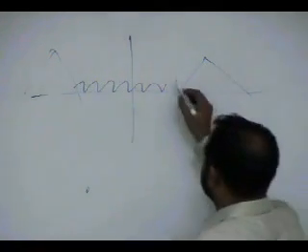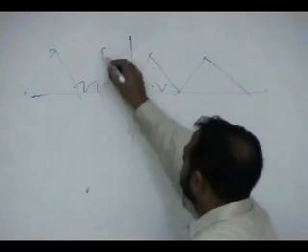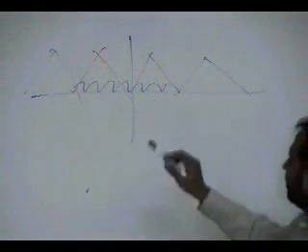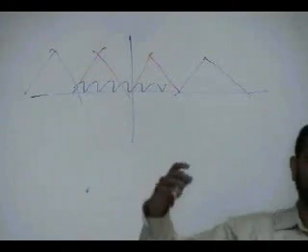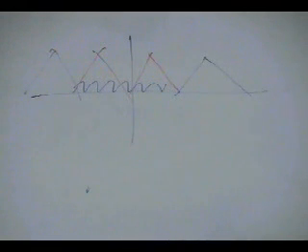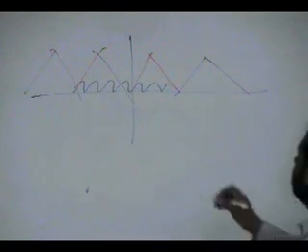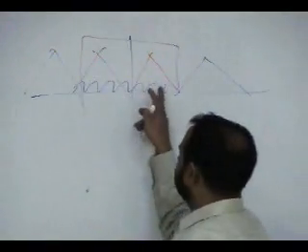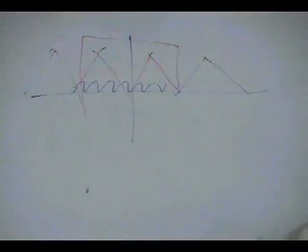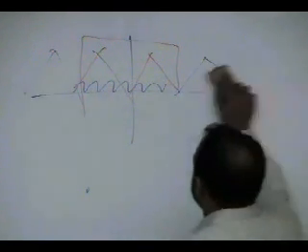Once you band pass sample, remember you are going to get a copy here and a copy here, which I just did. So there was already noise here. We call this out of band noise. It's the noise from the other bands. If that out of band noise is there, it's going to corrupt your signal, because once you sample it and filter it out, there will be noise in your desired signal. It's very tricky to do band pass sampling. Tricky in the sense that you really need to make sure that your out of band noise is no more there. But coming back to sampling, what I want you to really know is this.